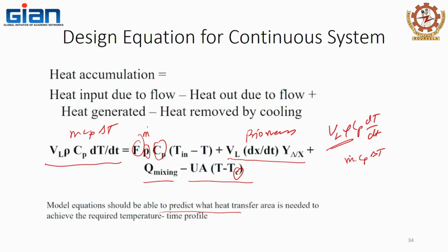So, if you are designing your bioreactor, and you know how much heat is being generated by the biomass and what the removal of the heat would be, you can design the area inside. You can add baffles if you want to improve the overall removal of heat. If you do not need that, you can change the number of coils that you will have. You can make a lot of these modifications to your bioreactor design depending upon what the heat removal requirement is.